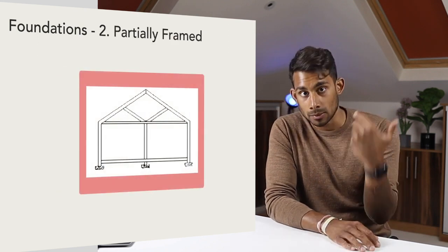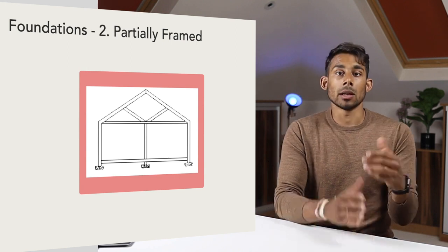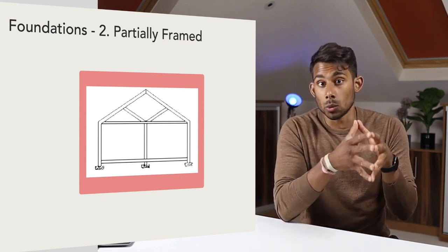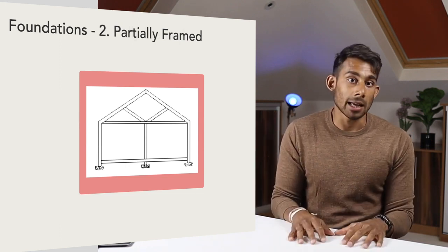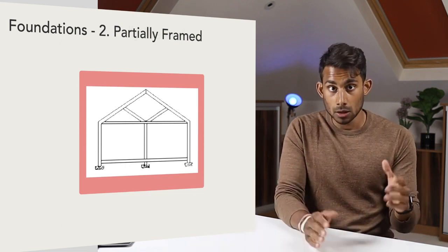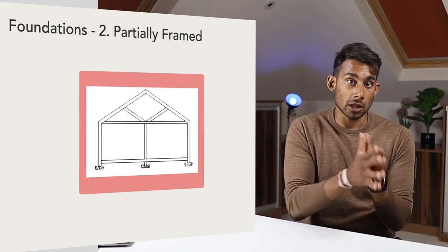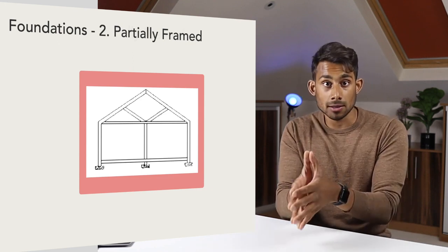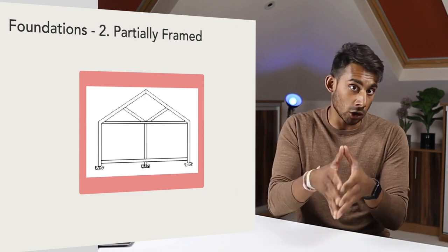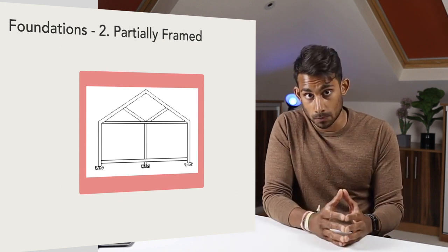Two, partially framed buildings. Partially framed buildings characterize those which are halfway between the framed and unframed, i.e. buildings containing a share of each. The external walls form the unframed section, as they are load-bearing, and the framed section comprises posts and beams erected to replace load-bearing internal portions.